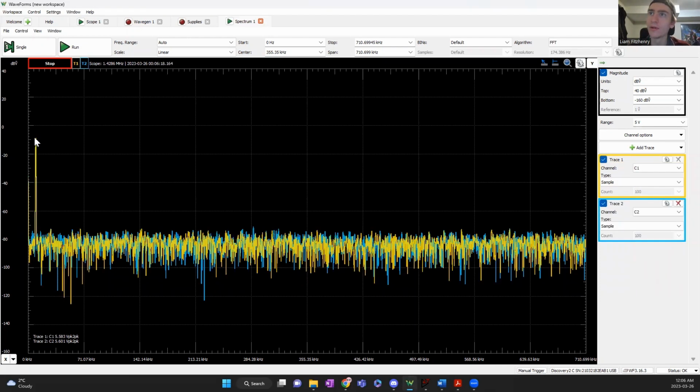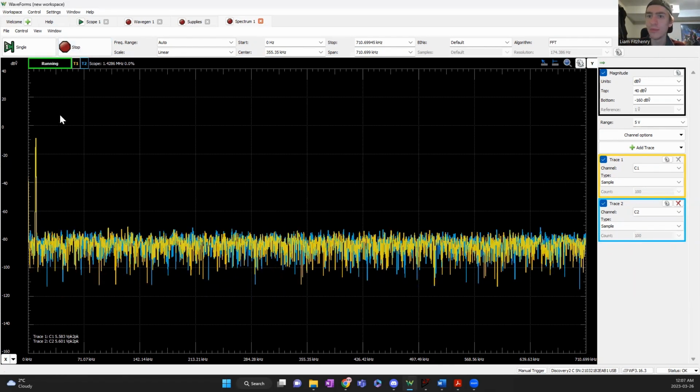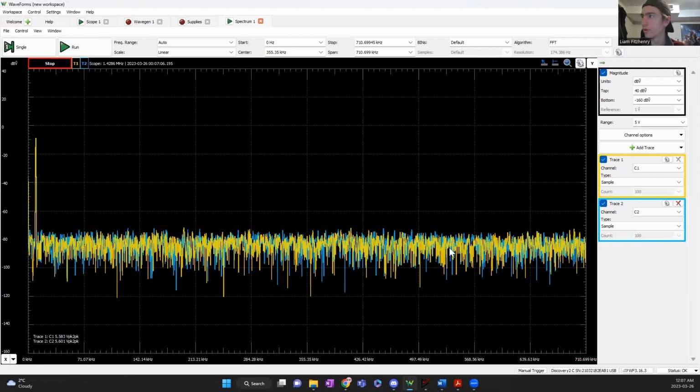And it goes to about -6 dBV, which corresponds to 0.5 volts. So that's what we expect. We expect both signals to be made up of mostly a 10 kilohertz sine wave. And as you can see, the rest of this, there's no real outliers. If I let it run, this spike remains constant here, but nothing else pops up. This is really just noise. So this is a good indication that our input and output voltages are linear and have a gain of about 1.